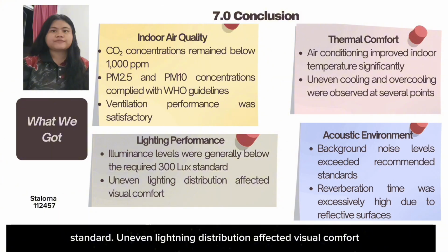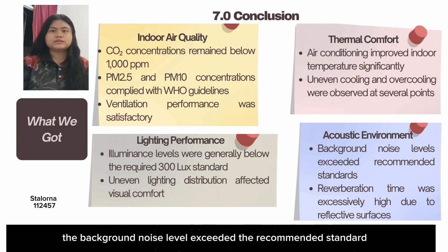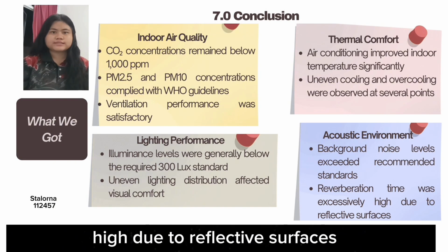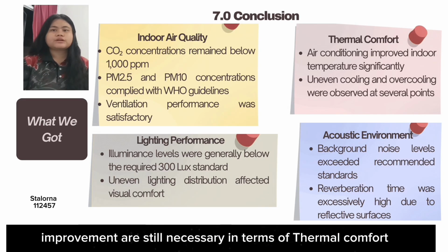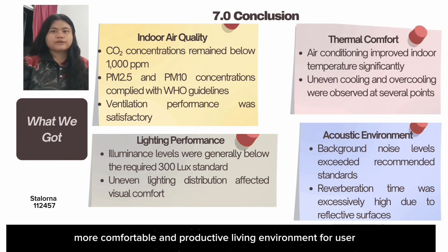Uneven lighting distribution affected visual comfort. Meanwhile, for the acoustic environment, the background noise level exceeded the recommended standard, and the reverberation time was excessively high due to reflective surfaces. In conclusion, although the resource center achieved acceptable indoor air quality, improvements are still necessary in terms of thermal comfort, lighting, and acoustics to provide a healthier, more comfortable, and productive learning environment for users.